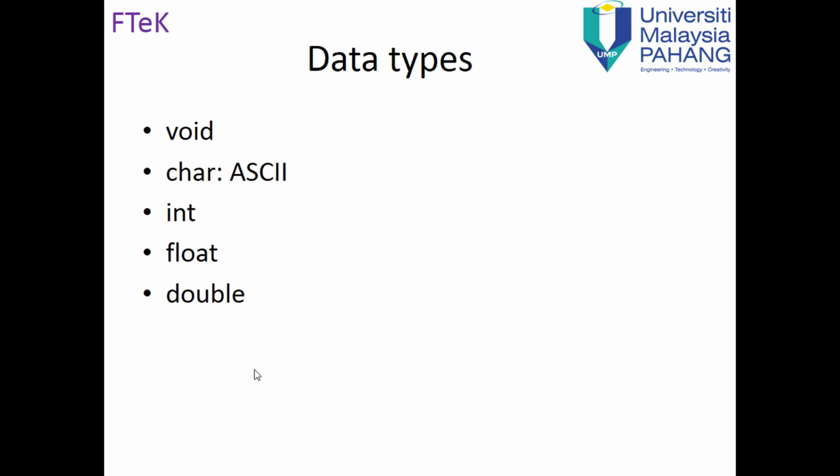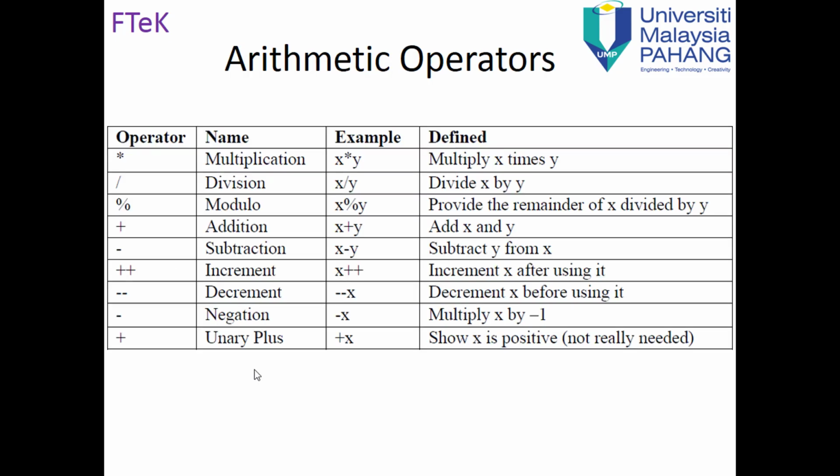Data types: we say that the microcontroller in the hardware only supports one data type, which is integer, signed or unsigned, an 8-bit integer. But here in C, using the library and the compiler, you can use all of these kinds. And don't worry, because the compiler will manage them and will allocate suitable memory for them. So it will use more than one place in the memory to provide you the facility of having these data types.